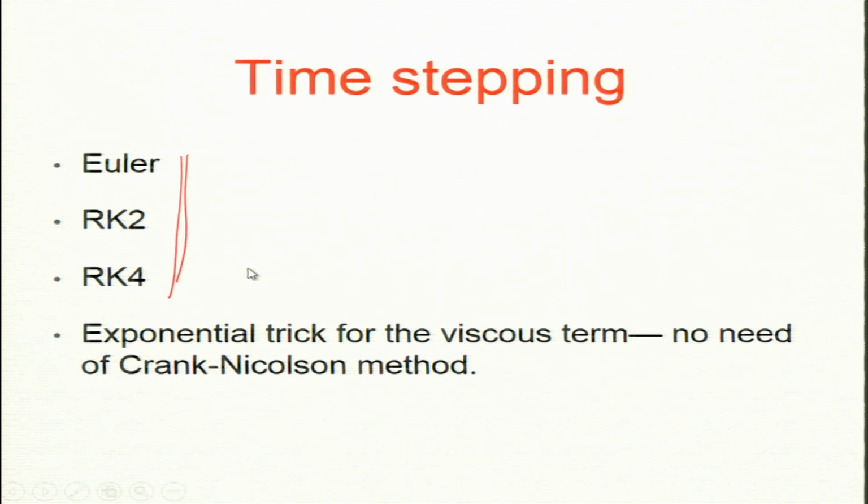One important point to keep in mind is that there are many time scales. Turbulence is a multi-scale problem. For every k there are at least two time scales. For u dot, one is the nonlinear term, N_k, and another one is nu k squared u_k.